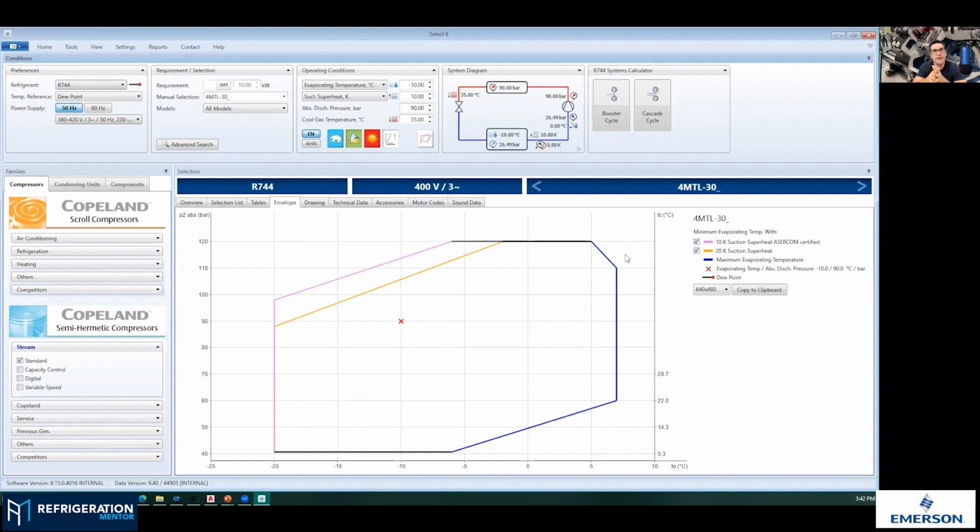Okay, yeah, no, I totally get that because you have internal protectors. So inside the compressor, you're overloading the motor. Are these PTC sensors inside the motors? Or are they internal line breaks? I can't remember. On recip compressors, it's PTC. Yeah, they're PTCs, right? PTC sensors which are wired to the terminal plate, and then either you use the compressor internal protector, which gives the signal that the maximum temperature of the winding was overstepped, or you can also read on some other compressors the resistance, and you can check it in the system